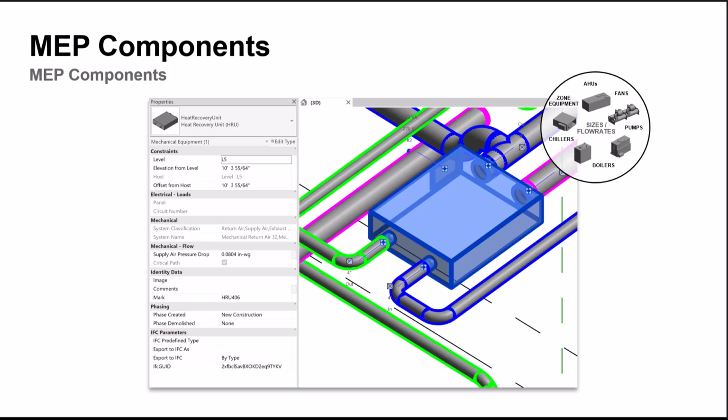In Revit, elements aren't just geometries, they are actually intelligent families containing key data through parameters. Parameters define, control, and display important information about building components. They make Revit models parametric, allowing elements to adapt based on these parameters. Unlike simple 2D CAD blocks, families store data that can be pulled into schedules or documentation, simplifying tasks like quantity takeoffs, minimizing errors, and aiding the creation of a digital twin.